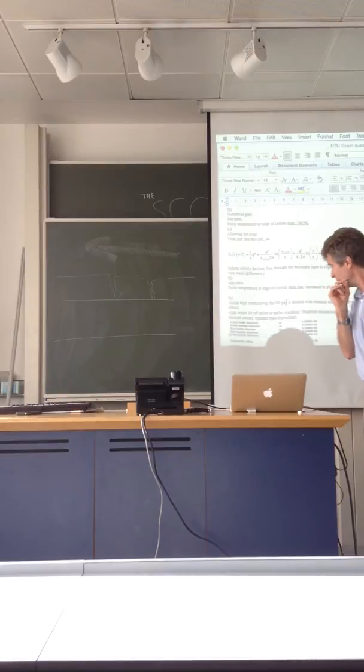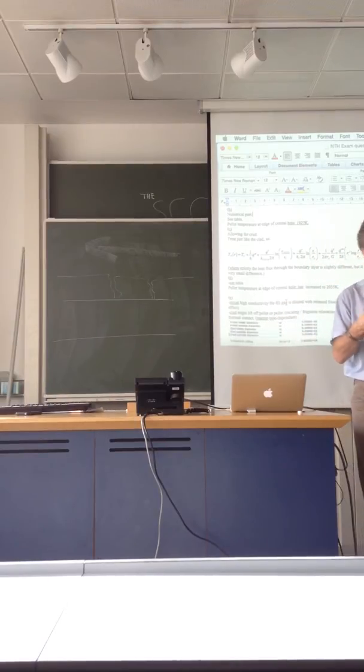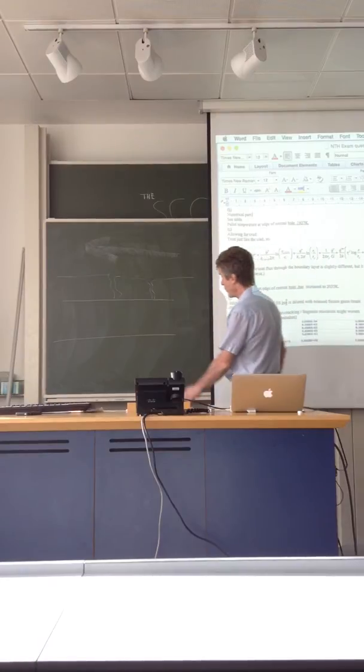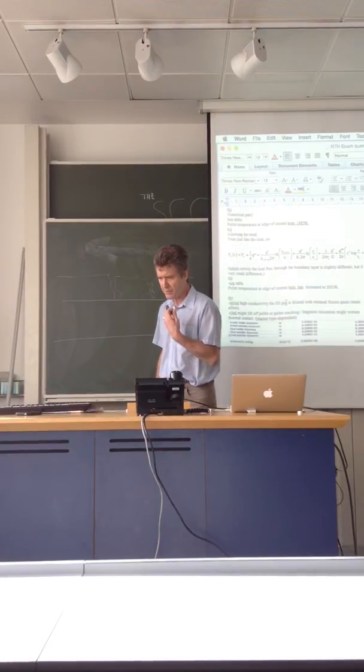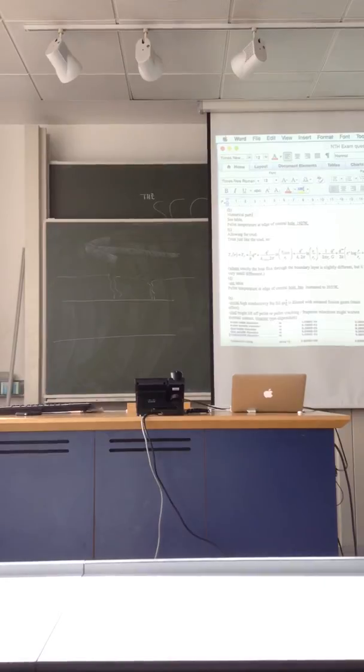We go through the equations, just to give you an example of the approach: conservation laws and constitutive relations, which is exactly the same again. What happens practically is that boron in the coolant, and we now know why boron is there, soaks into the crud and gets concentrated in it.